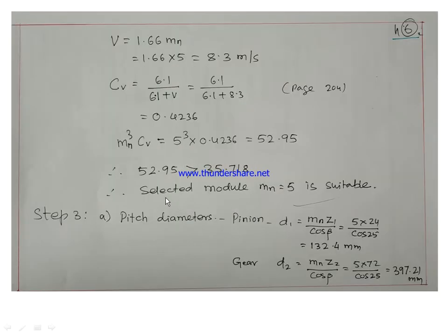Okay. Now whatever the module we have chosen, that is 5 mm, is suitable. So from the strength point of view the design is safe.